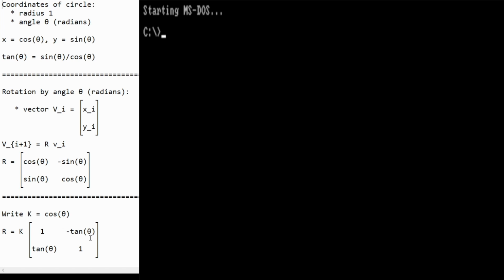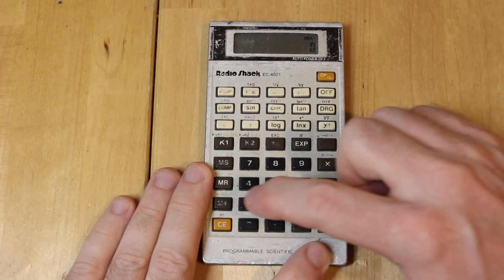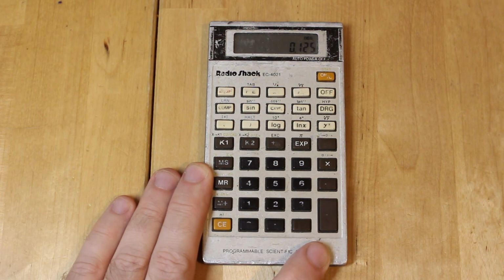I think I said I'd use either 1 on 8 or 1 on 16 as an example. And this matrix is then very simple to use, so long as we also multiply by this constant cos theta that we pulled out the front here. Before I do any coding, let me compute the k value that we're going to hard code into our program for the Cordic implementation. I've decided to use tan theta equals 1 on 8 for my code, and so let's put that in. That's the value 0.125, and the value that we want for k is cos of theta.